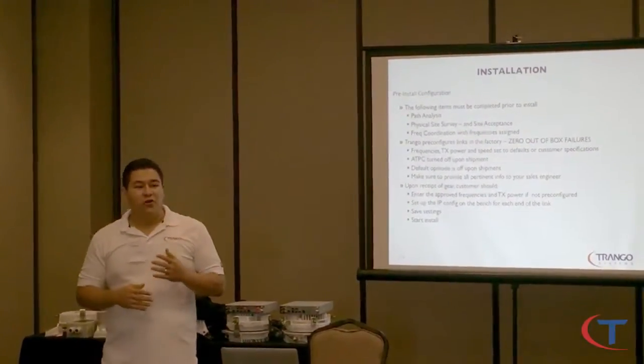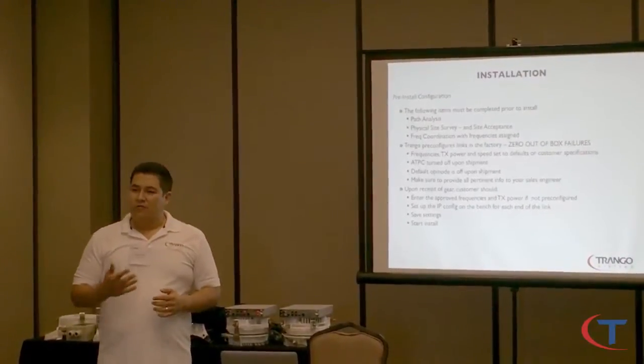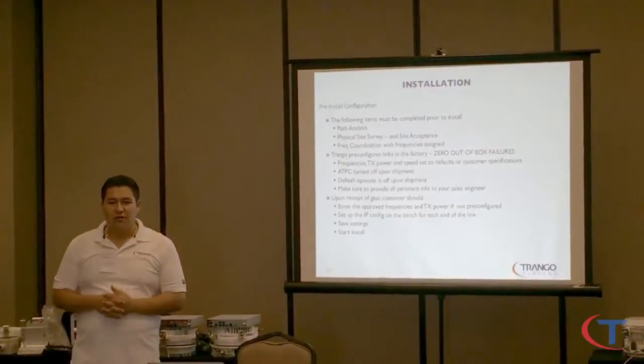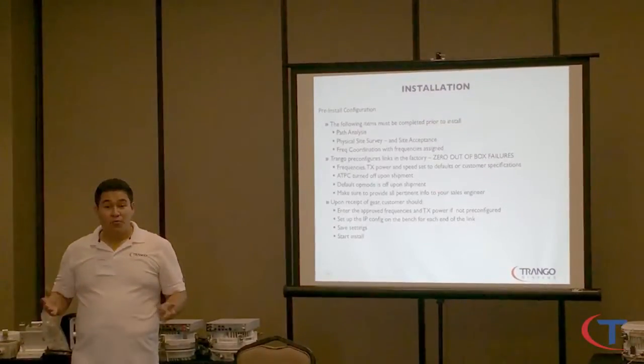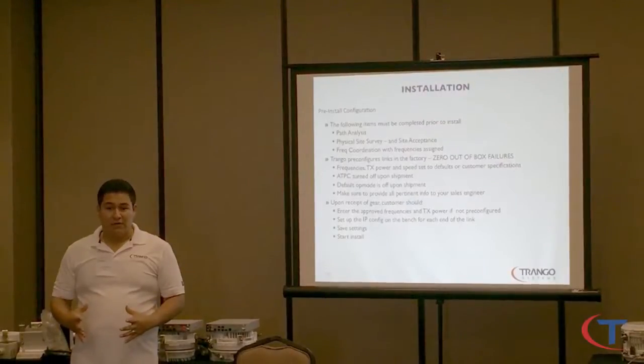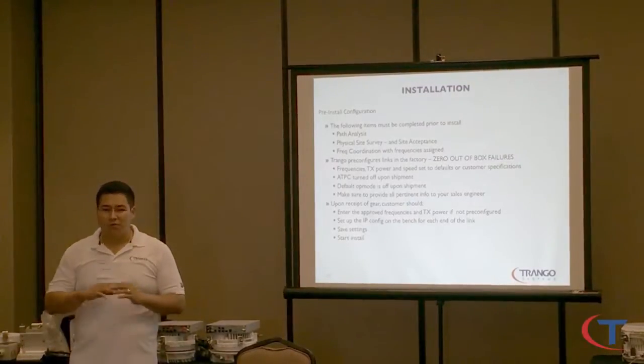Physical site survey is when you're going to lease space on a tower, you want to make sure that it's nice AC power, constant clean power, grounding is done properly. All the grounding has a common ground on the telecom site. If you don't want multiple grounds, that's going to be really bad.